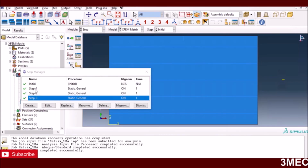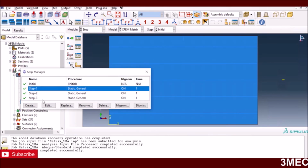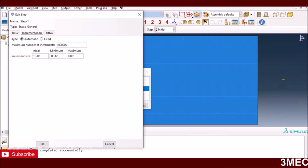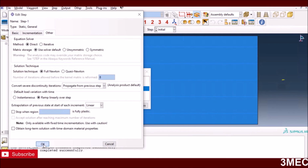Stepwise, what I have done here is I haven't modeled the whole thing again. I have modeled the loading part. So this is the first step where I load the sample. So I pull it from this direction as is given in the paper. I'm using the stabilization because I will have a crack propagation to avoid any convergence issues. I'm using a very large number of increments so that it doesn't stop if it reaches a big number. And these are the minimum, initial, and maximum time increment sizes I have used. Other things are default, so I'm not changing anything.